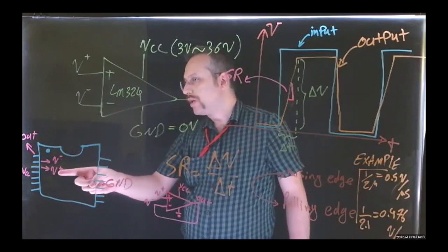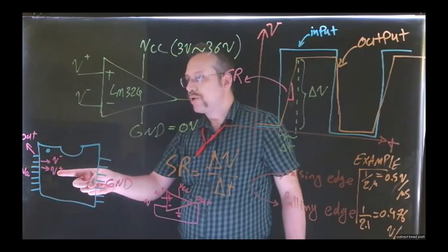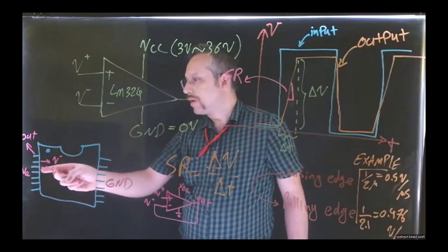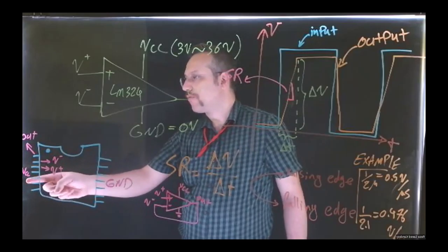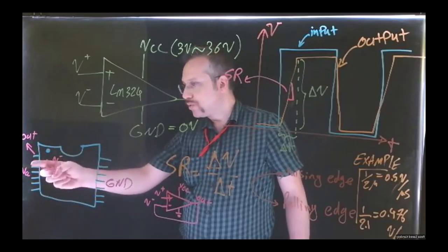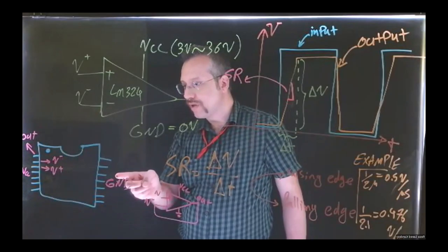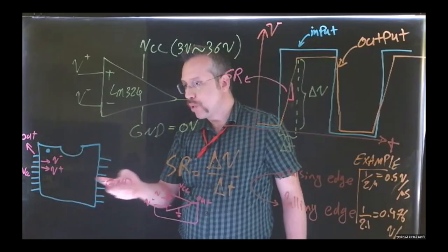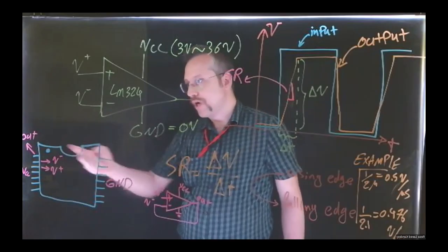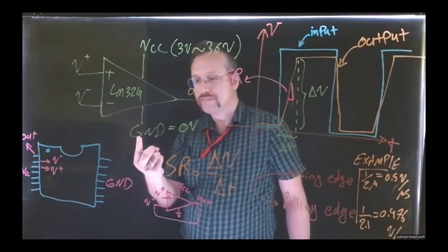The third one is the non-inverting input. And the fourth pin is the VCC port. Now, if you count 1, 2, 3, 4, 5, 6, 7, and then 8, 9, 10, 11, the 11th pin, which is the middle pin on the other side of the LM324, is the pin that you connect to the ground.